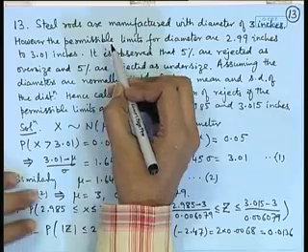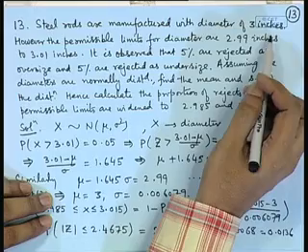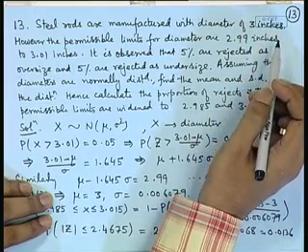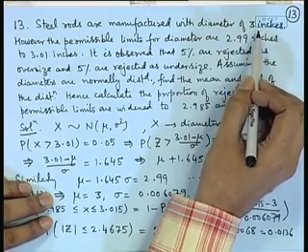Consider steel rods which are manufactured with a diameter of 3 inches. Now, in any industrial process, the specifications are given. So, here the specification is that the diameter should be 3 inches for the rods. However, in the actual manufacturing, there will be some deviation. That means, it may be 2.999 inches, it may be 3.001 inches, etc. So, in any industrial production, the producer or manufacturer or the customer specifies what should be his desired specifications, rather than telling exactly 3, because that may never be met.